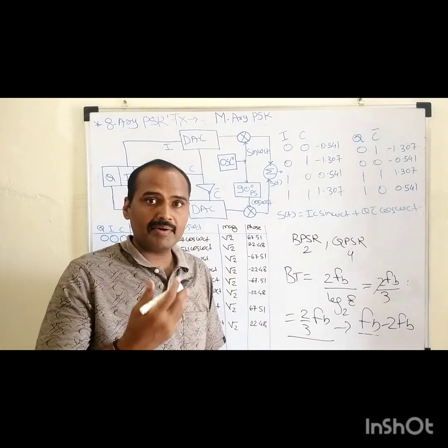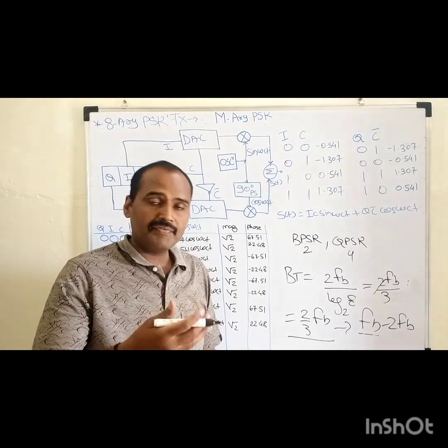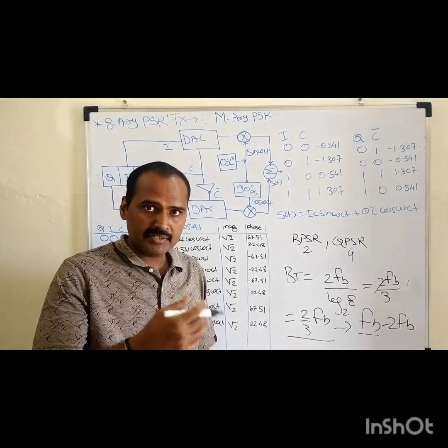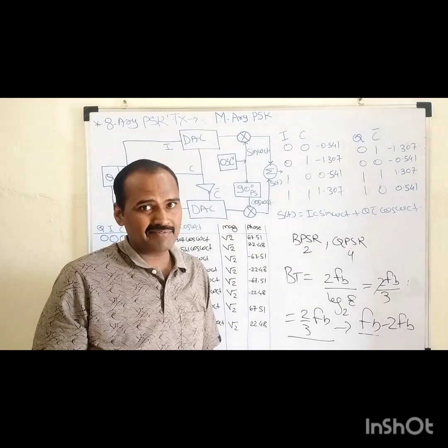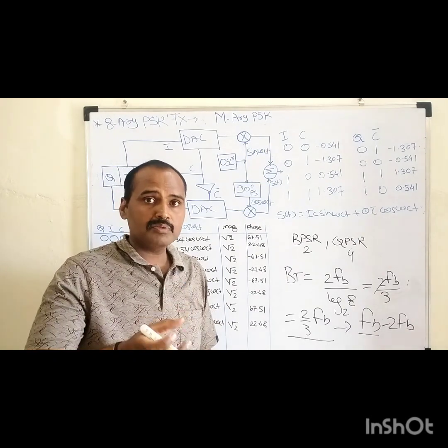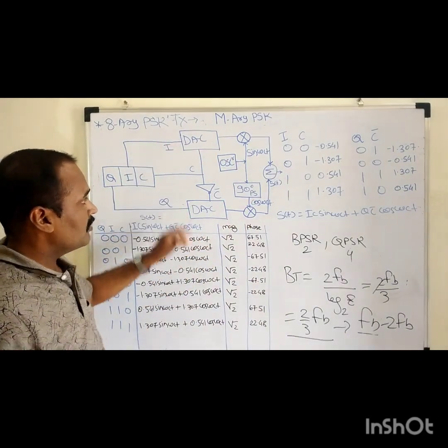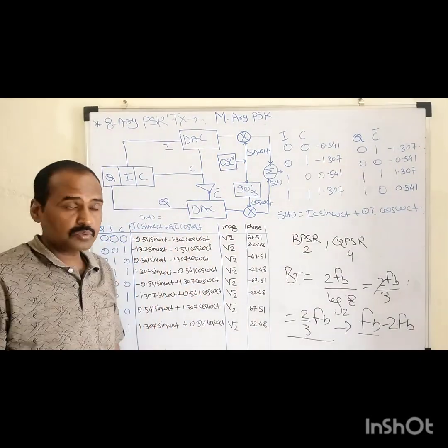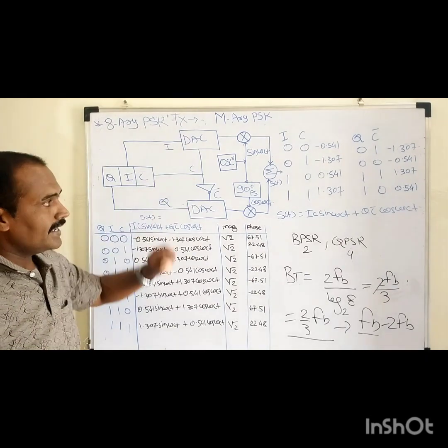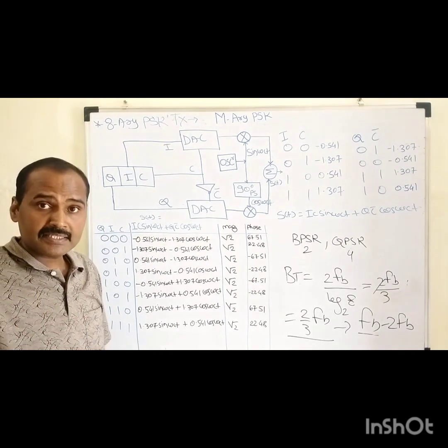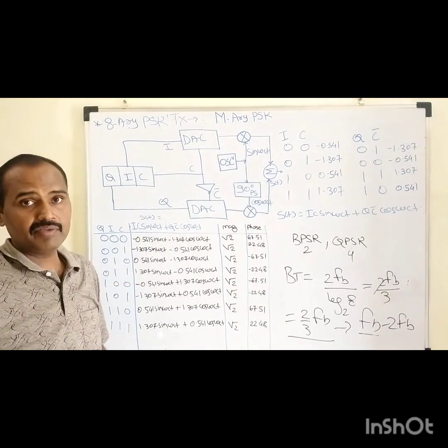Ultimately, our interest is to change the phase of the unmodulated carrier signal with respect to the digital symbol sequence. But here, as the number of symbols is enhanced, here M equals what? For the sake of this moment, M equals 8. So this is how your 8-ary PSK modulator, or the transmitter, will look.